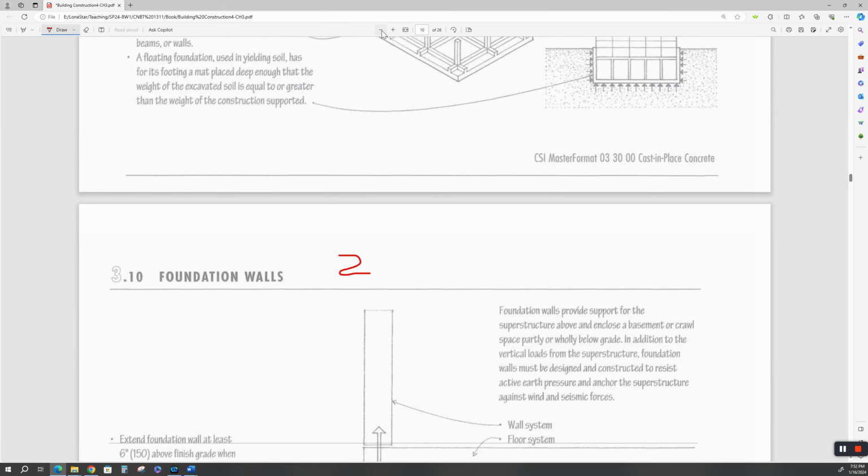This obviously has some groundwater issues, or there wouldn't be a subsoil drainage system with granular material. If you're going to do a French drain like this, you're going to need some kind of textile fabric, and there needs to be some waterproofing along this wall all the way up. Damp proofing, you use waterproofing, not damp proofing.